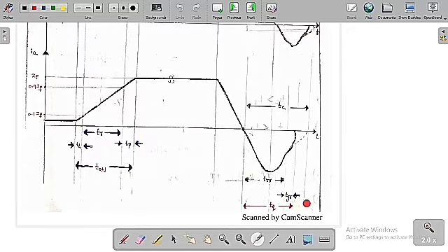And this overall summation is called TQ, and this is the TC from 0 to 0 value. This is the circuit turn off time. So this is the voltage. You can see clearly up to this time we have to give the reverse voltage across the device. Then only we can confirm this. The reverse voltage should be given up to this time, then only we can say the device is totally off. So always one thing is very important.